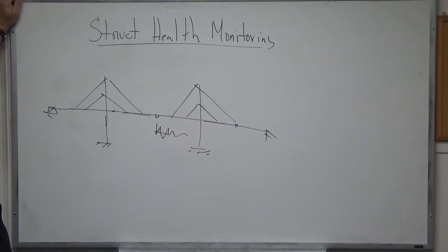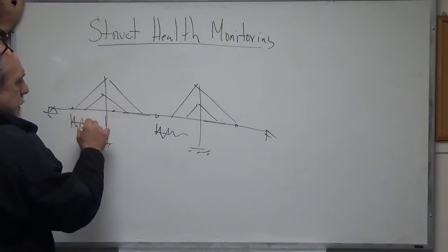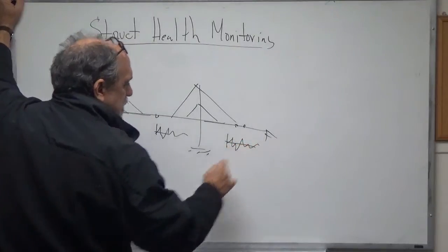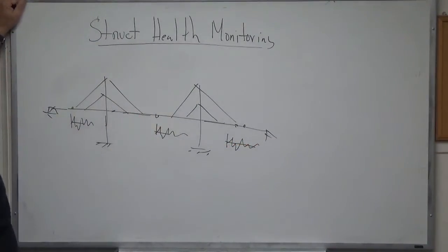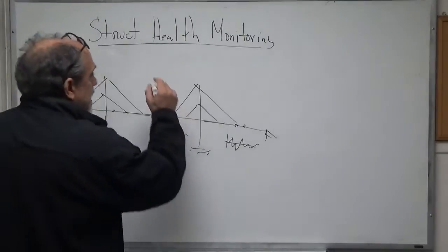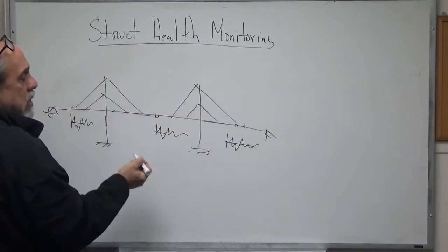Now, how can I do that? Well, with system identification, I may use the measurements that I have from my sensors, right? Now, looking at the sensor data directly is not very useful, right? Because every day I look at it and it just looks like a mess, right? A bunch of numbers, a gazillion things. I plot them. How am I going to know something's the matter? I don't. But what I can do is do system ID, let's say every day at noon, or at 3